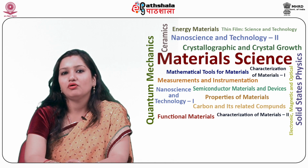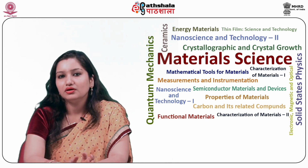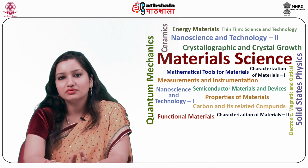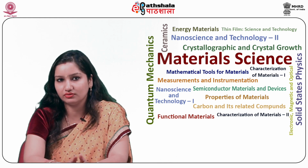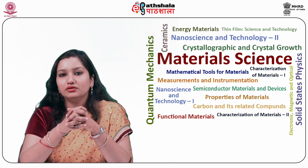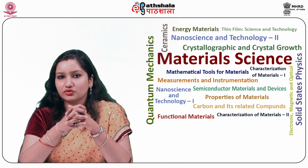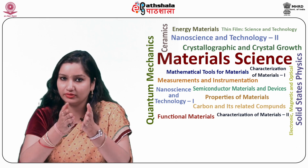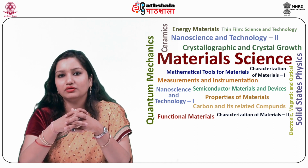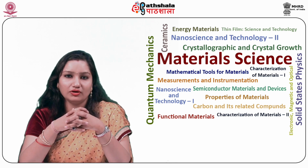On illumination of a conventional semiconductor-based photovoltaic cell, generation of charge carriers, that is the electron-hole pairs, take place at the depletion region, that is at the p-n junction of the semiconductor. The carriers thus produced are responsible for the generation of photocurrent, which can be harvested in a useful manner. The electronic band gap of the semiconductor determines the photovoltage produced by the photovoltaic cell.